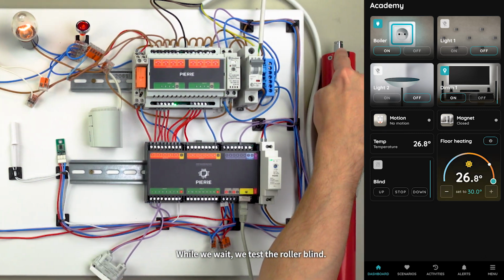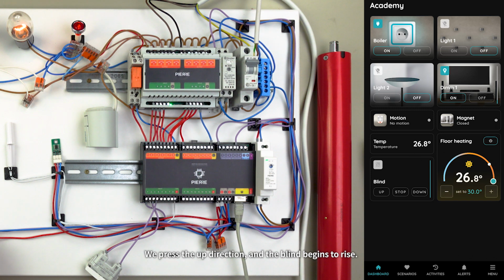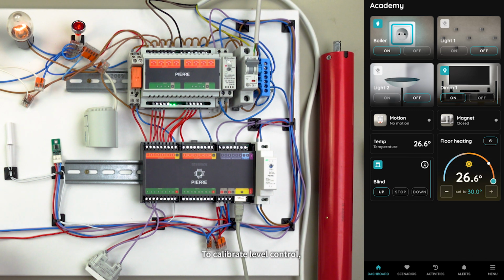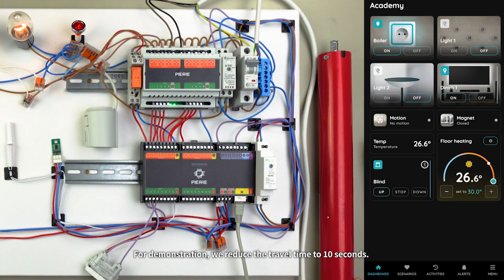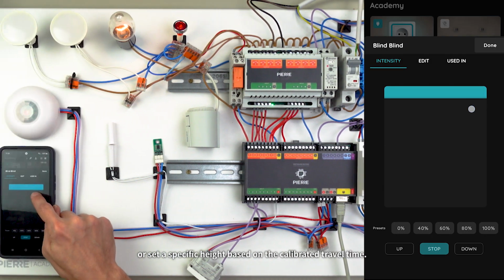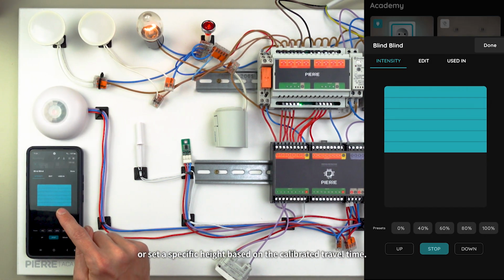While we wait, we test the roller blind. We press the up direction and the blind begins to rise. To calibrate level control, we must first allow it to reach its end position. For demonstration, we reduce the travel time to 10 seconds. Once calibration is complete, we can adjust its position using the level control, move it up, down, stop midway, or set a specific height based on the calibrated travel time.